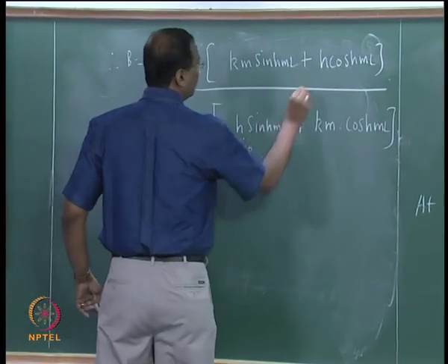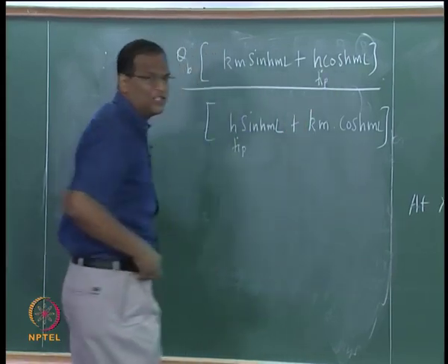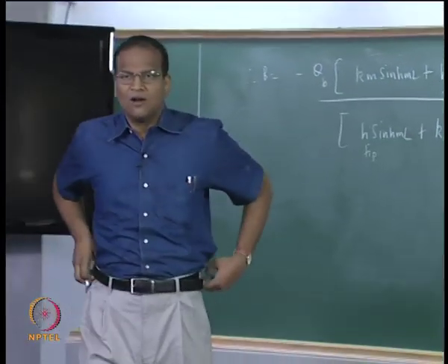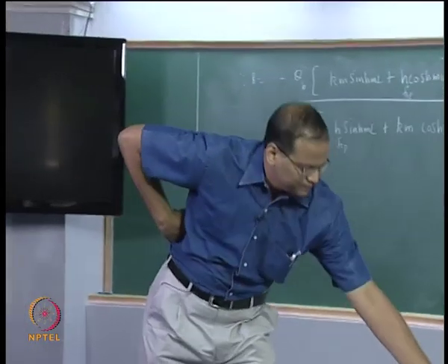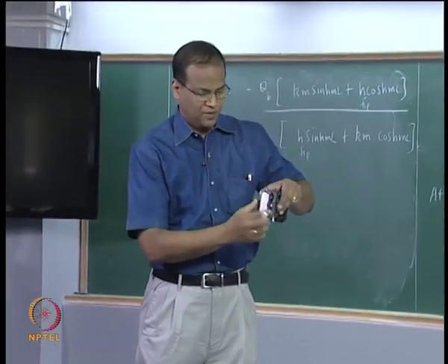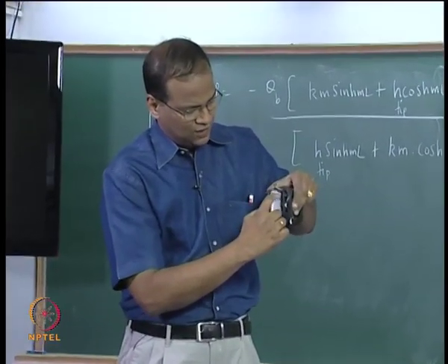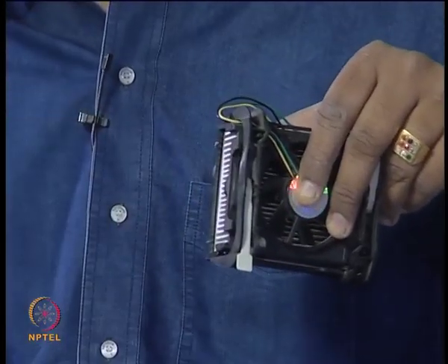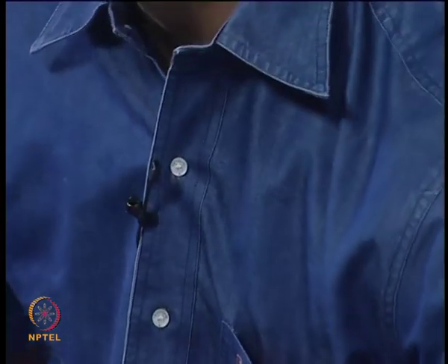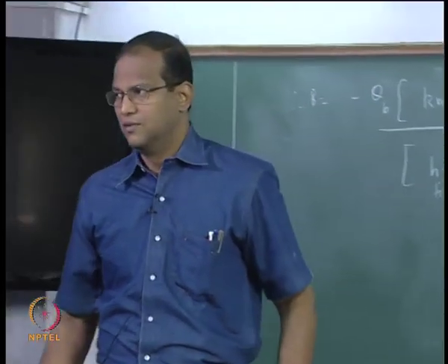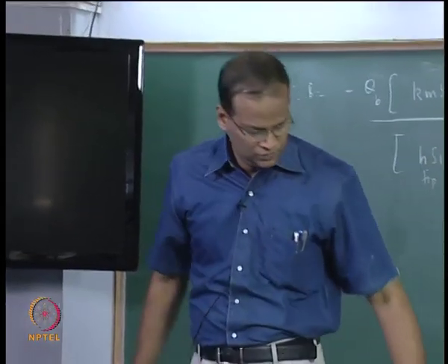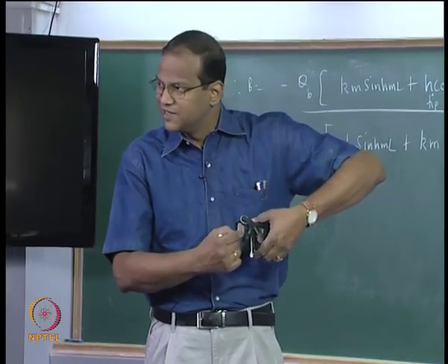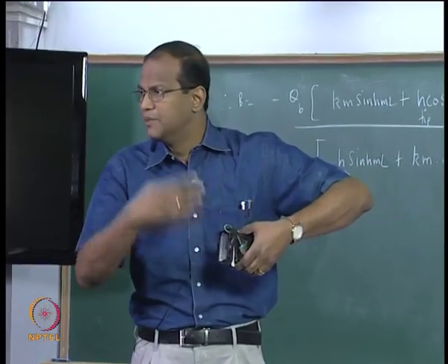Because the tip heat transfer coefficient could be different, because it may be a combined convection and radiation, or because along the fin it is heat transfer from a horizontal surface, but at the tip it is heat transfer from a vertical surface. There could be small differences. Okay, the tip is a vertical surface, isn't it? So the heat transfer from a tip is applicable.